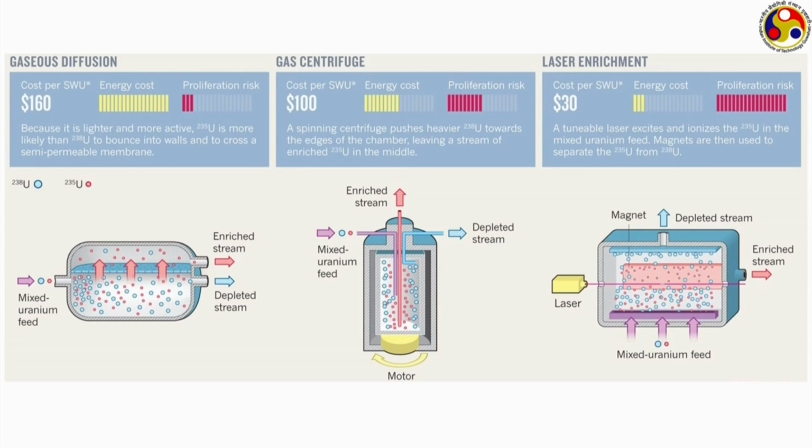But of course, just one membrane step is not sufficient; a diffusion process can involve a few hundred, maybe more than 1000 such membranes, all having the same dimensions, sometimes with small differences in their nature. Ultimately, on one side of this membrane or group of membranes we get enriched fuel, and on the other side we get the depleted fuel.